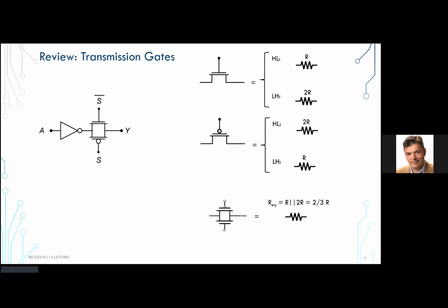It has to be a low resistance path to ground in either case. And we're going to compare what is that resistance of the path to ground to a unit inverter. And this is the only way I can find that out. Otherwise, it's undefined. It becomes driver dependent, which is something that is important to keep in mind when we look more into flip-flop design and stuff like that. All right.